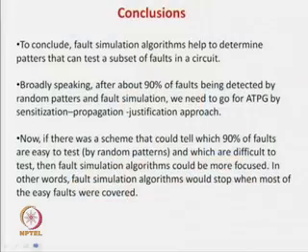So, that was about the fault simulation. To conclude, we can say that concurrent fault simulation helps in random test pattern generation. We apply some random patterns and then find out which faults can be detected by them. You can use serial, which is the slowest one. You can have parallelism: if your computer supports a lot of parallelism, then you can go for parallel fault simulation. Otherwise, you can go for deductive fault simulation or concurrent fault simulation.